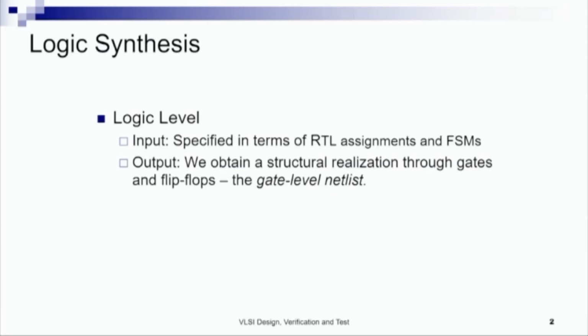The objective of the logic design or logic synthesis, on the other hand, is to obtain the micro level architecture of the circuit in terms of gates and flip-flops. So, the input to the logic synthesis step are in terms of the RTL assignments and FSMs. At the output of the high level synthesis step, we obtained a set of register transfer level assignments, and we said that the controller FSM will control at which time step which of these RTL assignments are to be excited or activated.